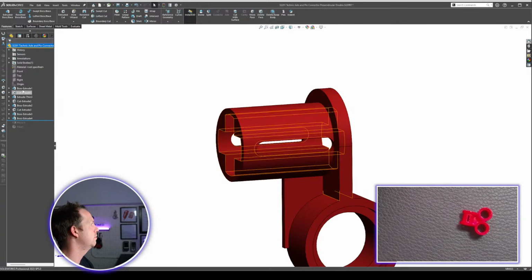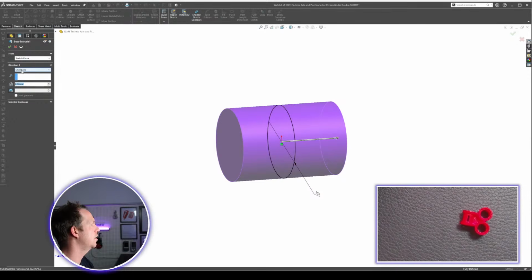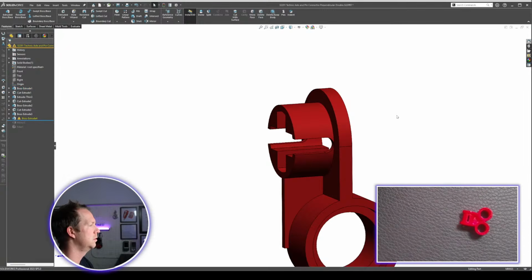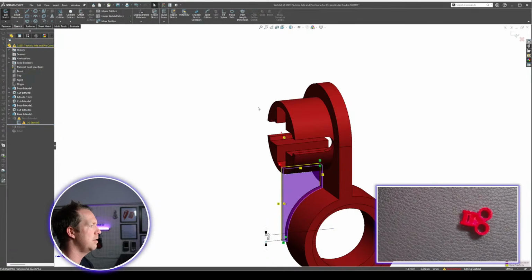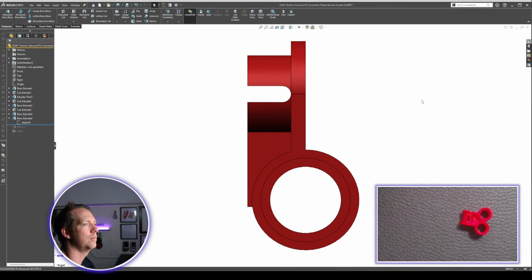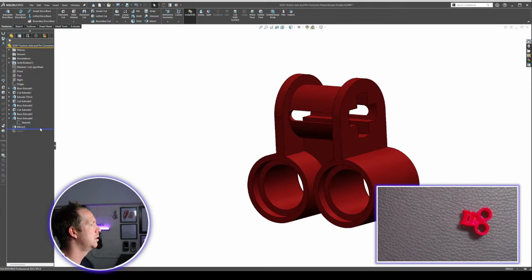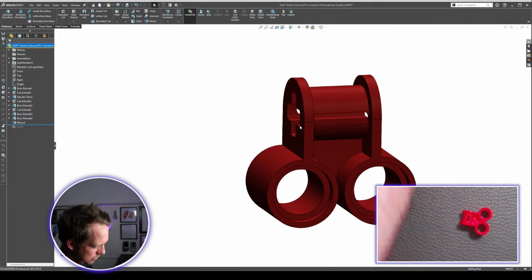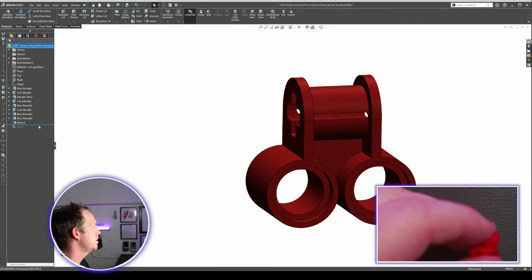Okay. Let's get even more efficient. And instead of going mid-plane, we'll just go blind 4. Okay. Looking pretty much more efficient now. Delete that midpoint. All right, now when we roll down and do the mirror, it's a much better result this time. All right, is it? Just probably a couple of small things.